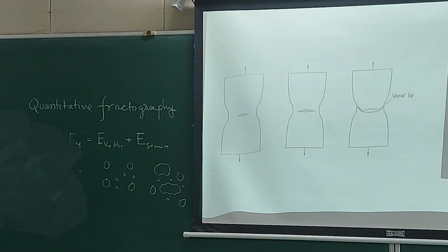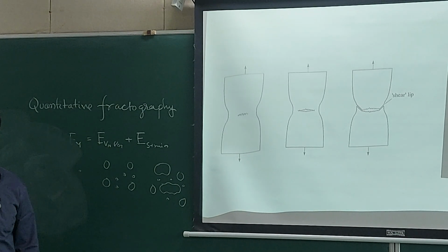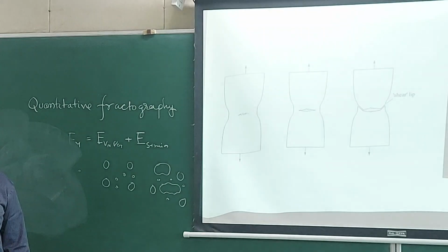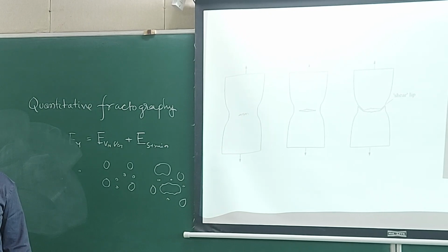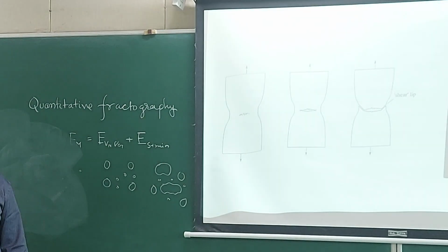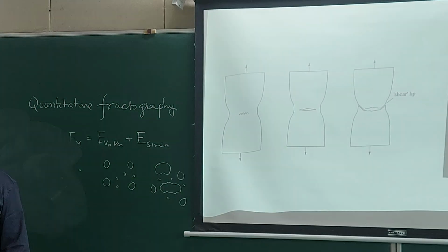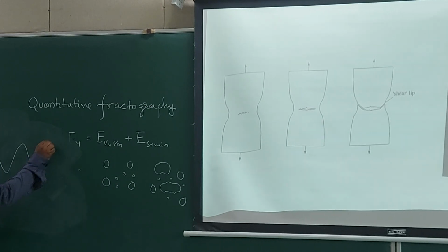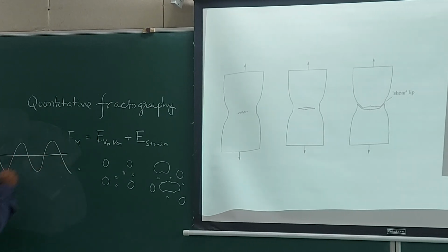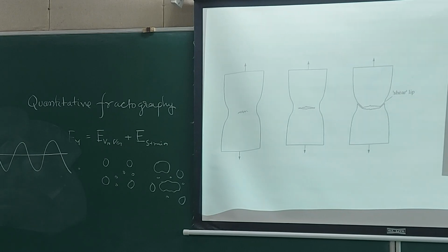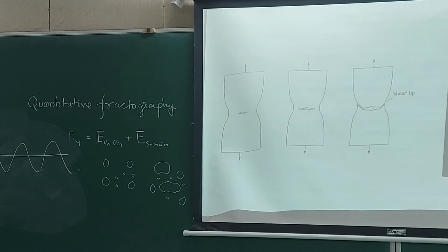Apart from that, you can also use a laser profilometer which will scan the upper surface and tell you the elevation. It will exactly give you the XYZ coordinates of the mountains, so crests and valleys, and from that you can calculate an average roughness value. So if you have something like this, then this is your roughness. Apart from that, there is something which is very unique.